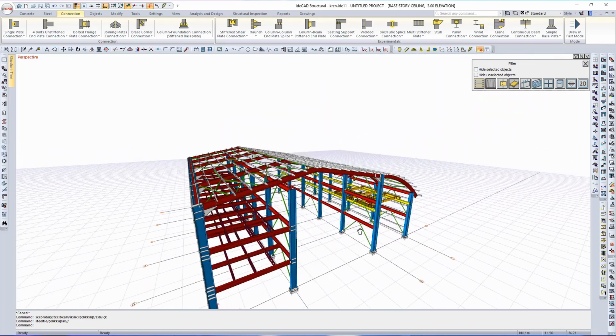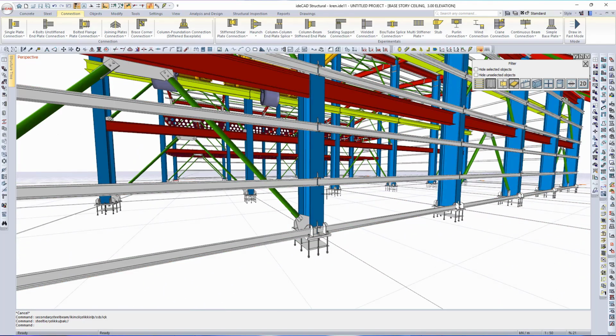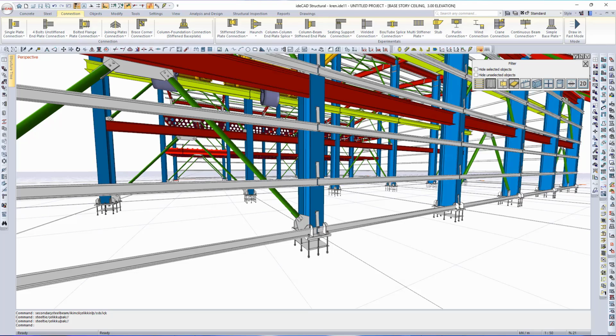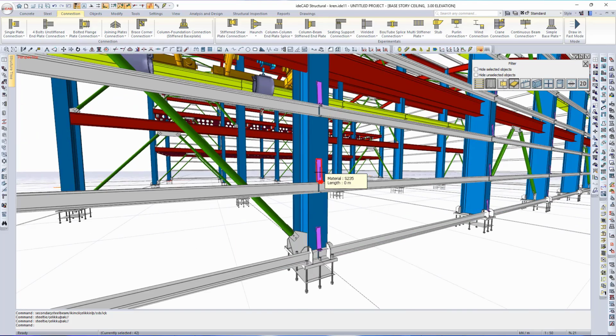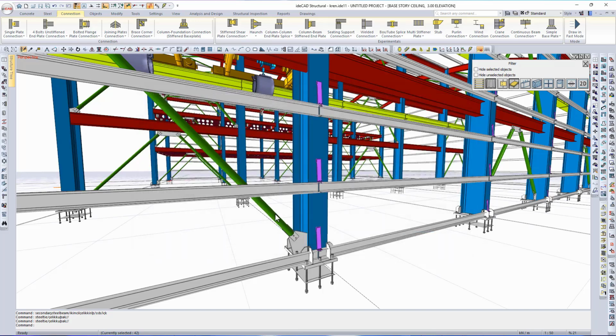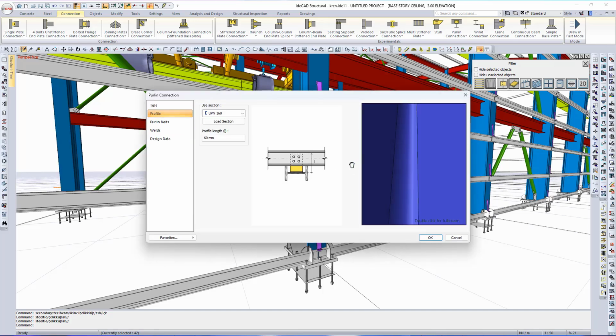After making the adjustments, I'll repeat the same process for this other purlin group, which hasn't been modified yet. I clicked on one purlin connection, selected Purlin connection, and then used Ctrl+click to select the rest. By applying a saved favorite connection, I quickly completed the modeling process.